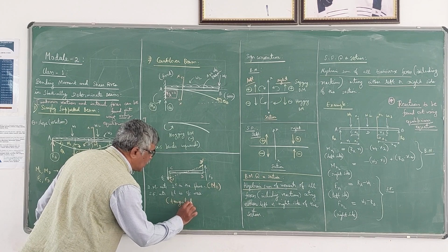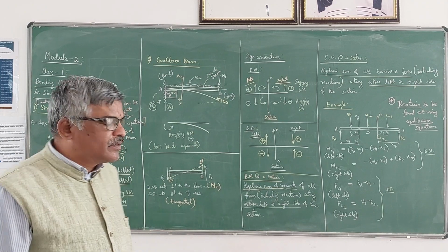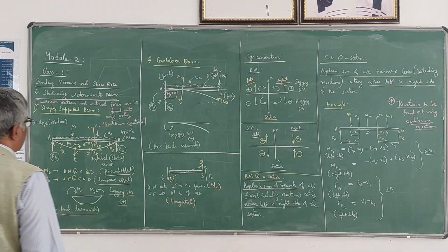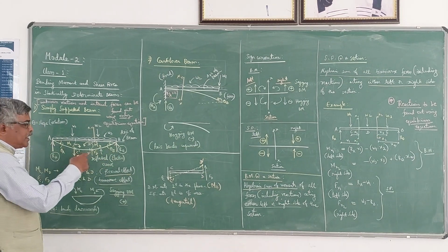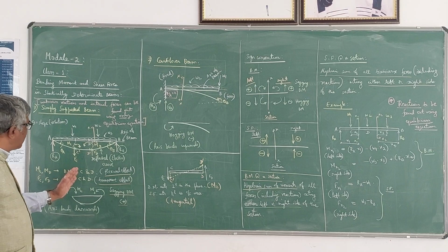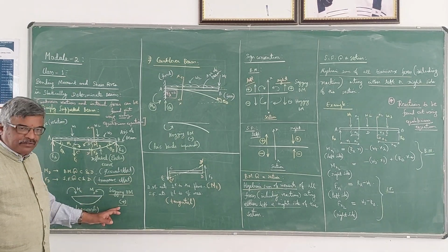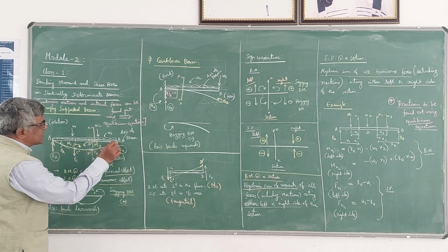So these two major effects we have to discuss in the case of a beam subject to different types of loads. In the case of a simply supported beam, this is how the bending effect will be, and we say that this type of bending moment is called sagging bending moment, which we take as positive in the analysis. And you can observe here, this axis gets deflected.